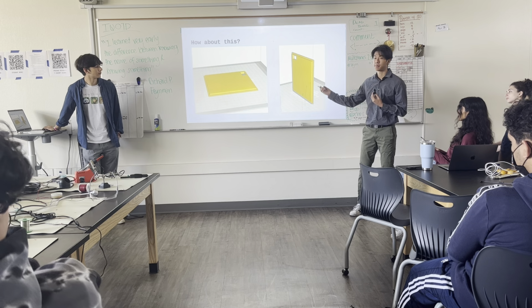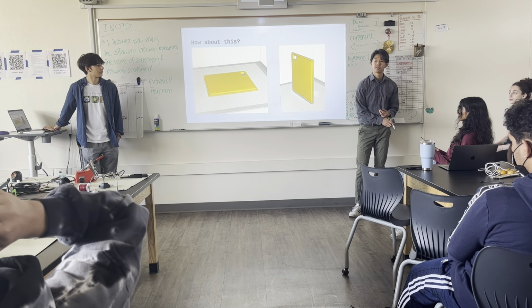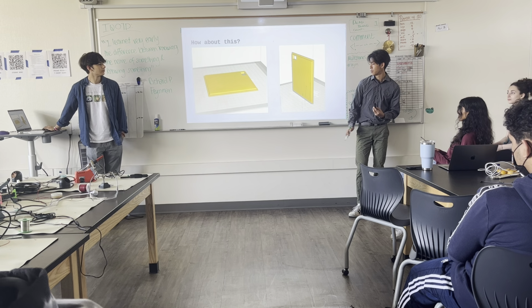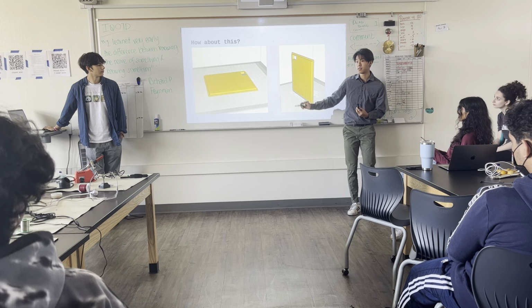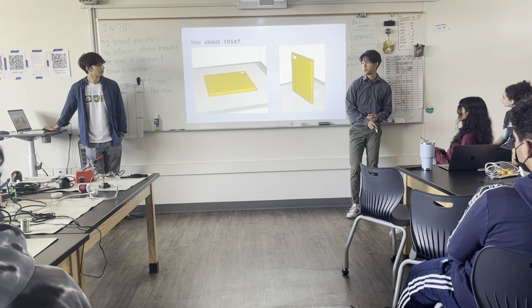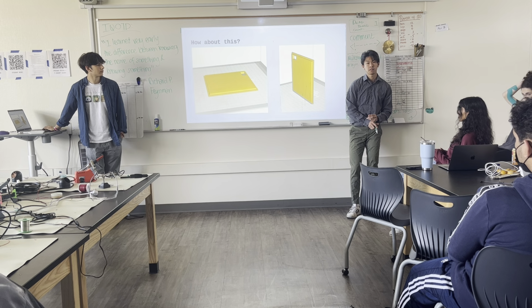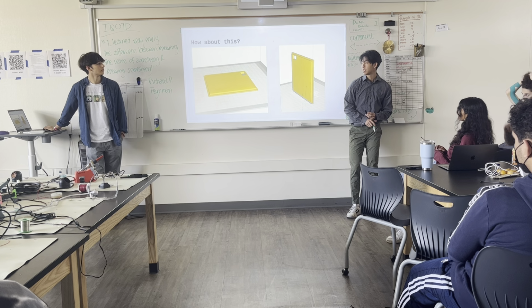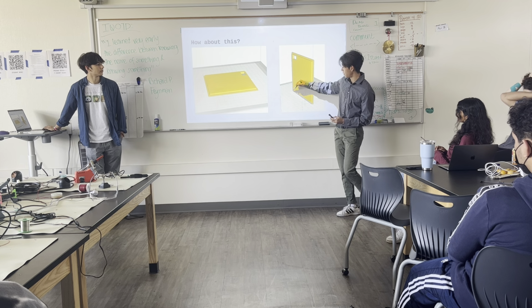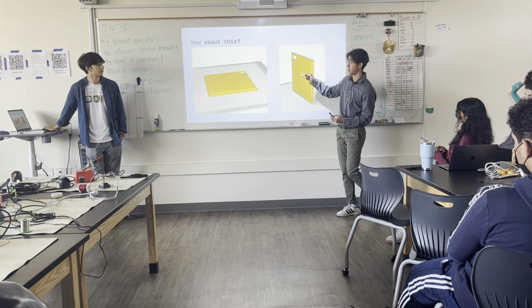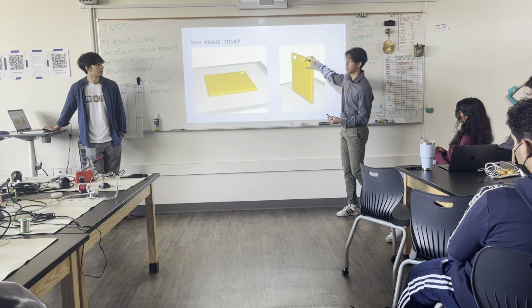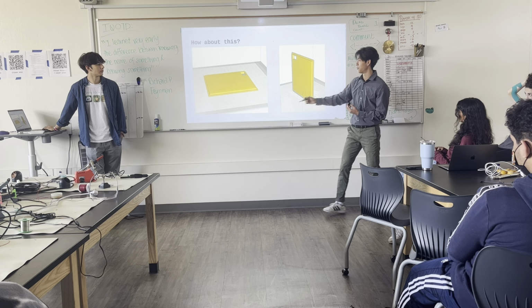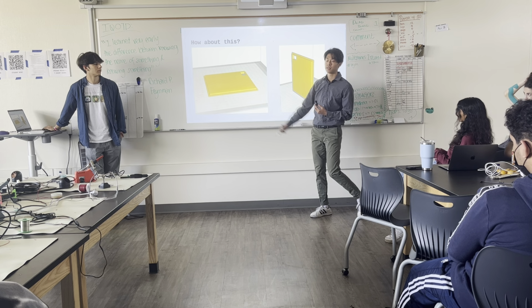Yeah, so is there something wrong with this? This doesn't really have supports, right? Maybe a tiny bit for the edge right here. Is one better than the other? Yeah, that's right. So when printing, there's very little bed adhesion here, and like you said, center of mass is higher. So when the printer's moving around up here, it might push the piece off by accident. So it's way better to print it like this, where it's more stable.